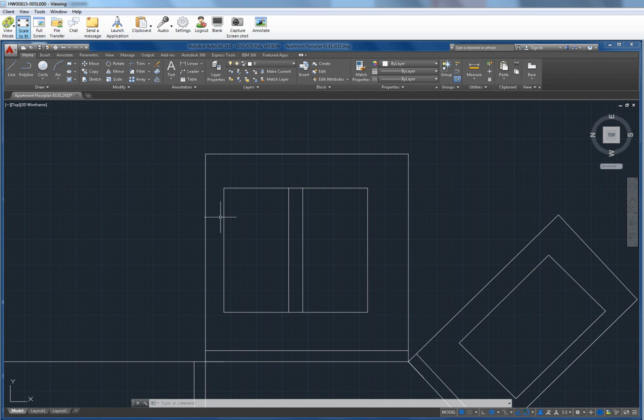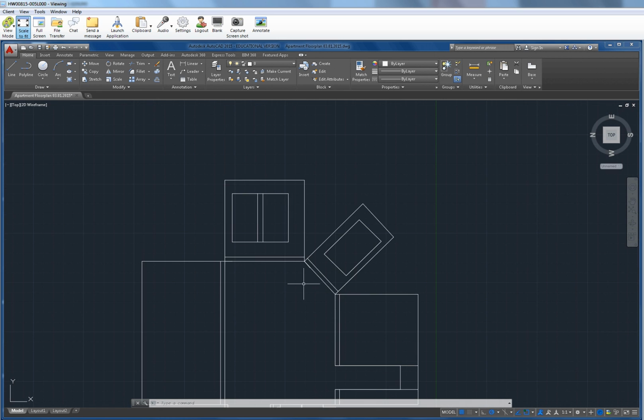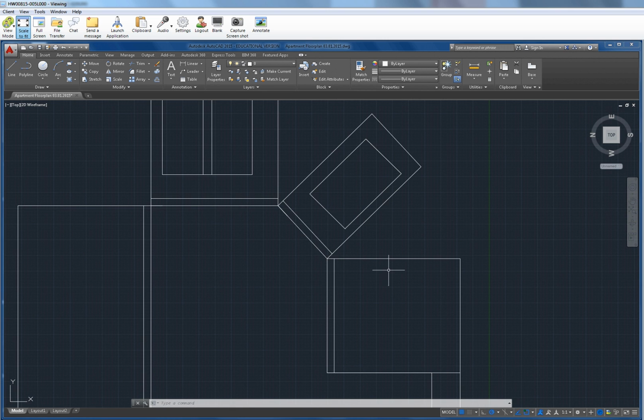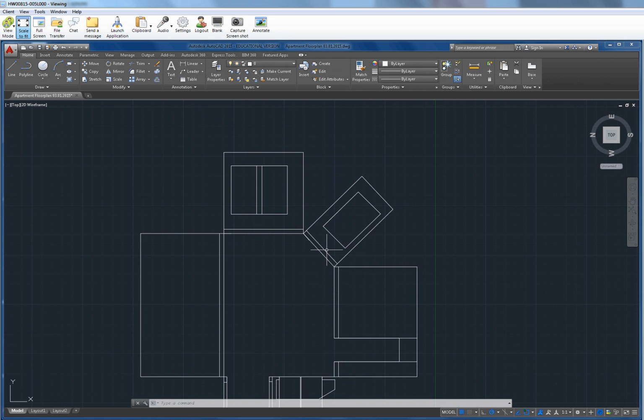I assume you guys are doing this as you're drawing these, I hope. It does help, right? Drawing upside down doesn't make the most sense. So as you guys work on these elevations, you can flip the UCS as you go. And if we have 45s, we can deal with 45s, right? Or if we don't have 45s, what do we use to quickly align? UCS entity. Right? UCSE, remember? Okay. What's that?